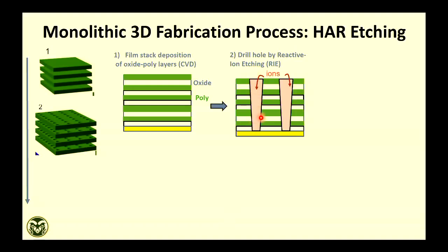So you're creating a cylindrical space through this stack, right? And those gaps you can see, hopefully, on this slide. So those are the holes that you're etching. What are the dimensions? Because if you know the dimensions, then you will understand how difficult it is to make. This whole diameter will be, say, 80 nanometers. This small hole, 80 nanometers. And the height for one layer is also, say, 40 plus 40. 40 is for this word line. The green 40 is for this oxide.